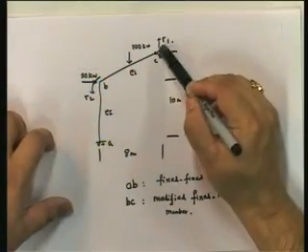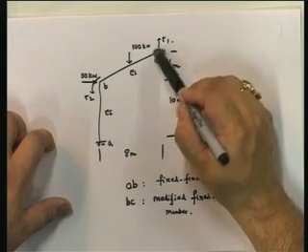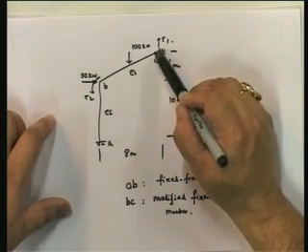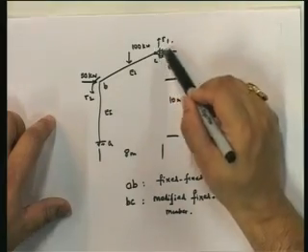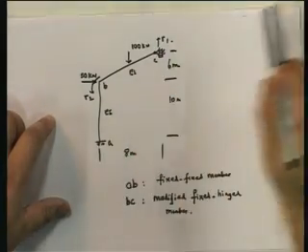So, now we come to the next problem that we have. If you look at the next problem, this is the problem. Identical loads, the only thing that we've done is we've removed the fixity over here so that the moment at this point is 0, so that it becomes essentially a hinge roller support. Fixed support, hinge roller support.